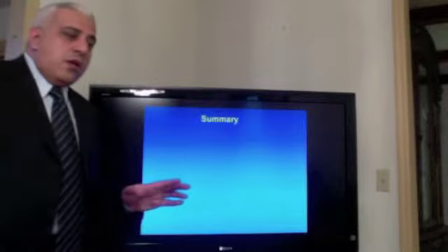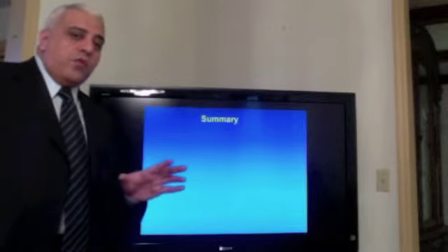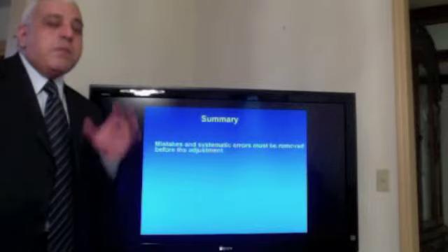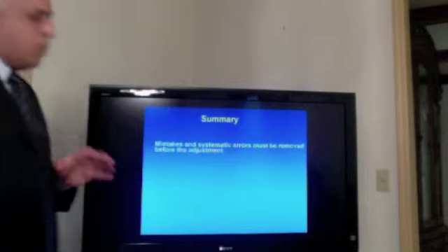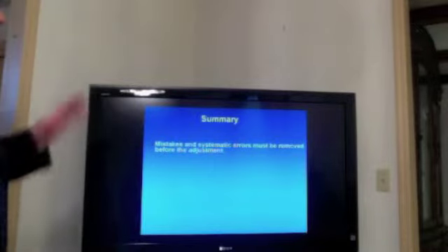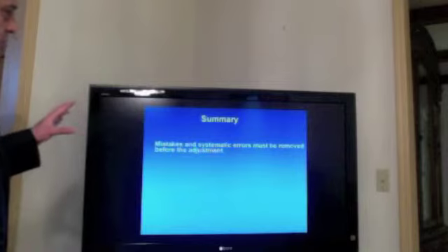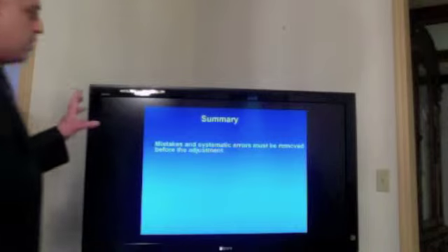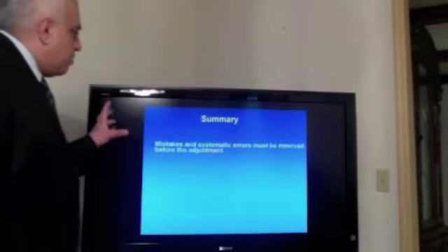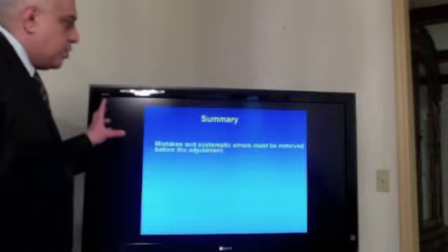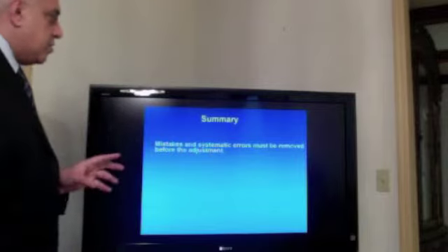Now, before we finish this presentation, let me summarize the main principles we need to stress. So, adjustment is the process where we deal with a certain amount of error. No systematic errors should enter the least squares adjustment.